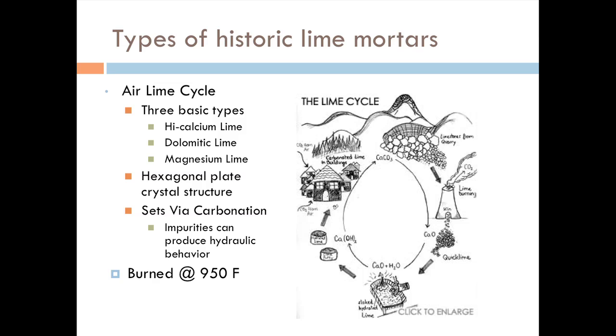But when you burn the limestone, you get something called quicklime. During the burning process, the CO2 and water are driven off from that calcium carbonate. So now you have this stone that weighs actually 33% lighter. And it doesn't look like anything else. It looks like the stone that you pretty much put into this kiln. But it's highly reactive. If you were to add water to this stone, it would turn that water into a boil. And that stone would start to melt, and it would turn into a putty. And that's where we would get calcium hydroxide, or lime as we know it.